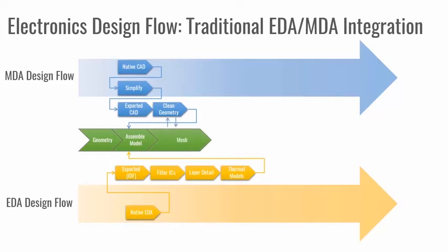Traditional CFD meshes the surface first, and then the flow space, and is error-prone as features of the geometry can cause the meshing algorithm to fail, necessitating more work to clean the geometry. And if that fails, the CAD geometry must be simplified further, re-exported, and the cleaning step repeated before meshing can be reattempted.